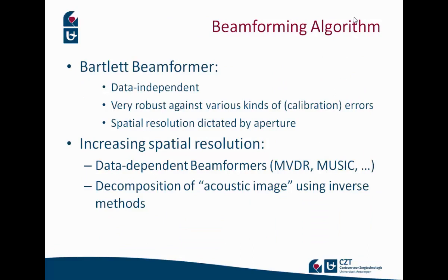The only problem with this type of beamformer, or one of the problems, is that the spatial resolution you can get with your array is dictated by the aperture alone. You don't care how long you measure, you won't get any better localization results. So there are different other types of beamformers presented in the past, like the Capon beamformer or MUSIC beamforming,